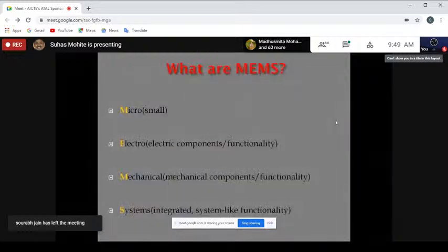So now let us move on to MEMS and MEMS technology. For the past 2 days, you know that MEMS is micro electromechanical systems, which are integrated systems. The functionalities are integrated. The components are exchanging signals across the boundaries of the domains: mechanical domain, electrical domain, fluid and thermal domain. 2 days back, you saw the thermoelectric tweezer, an example given by Professor Anand Suresh. So in the mechanical domain, you have structural, thermal, and fluids interacting with electrical quantities such as capacitance or changes in capacitance, inductance, or resistance changes, which in turn are converted by some kind of sensors.